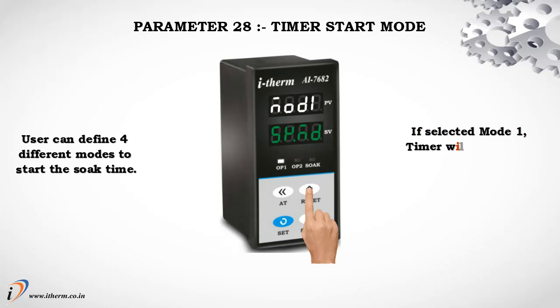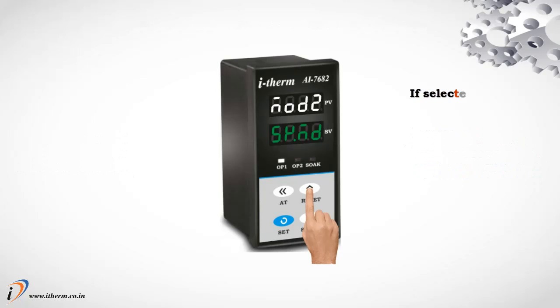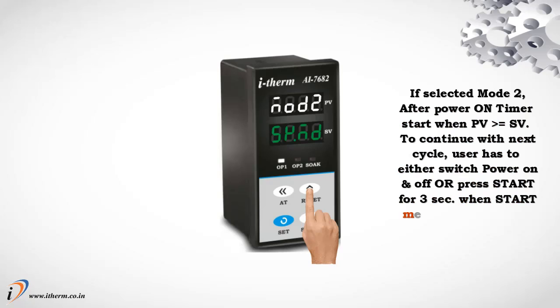If selected mode 1, timer will start after pressing start key for 3 seconds, irrespective of process value. If selected mode 2, after power on, timer start when process value is greater than and equal to set point value. To continue with next cycle, user has to either switch power on and off or press start for 3 seconds, when start message is displayed on the lower display.